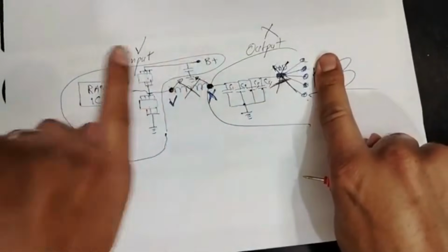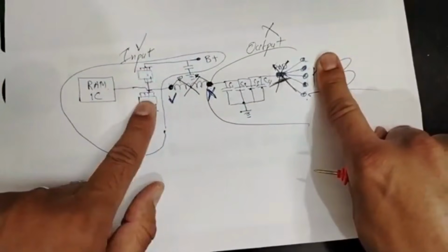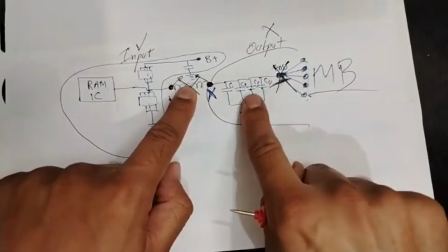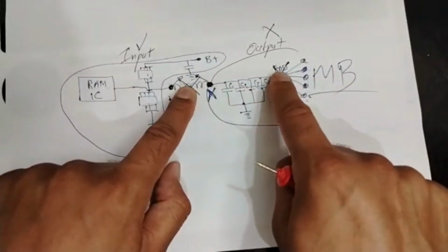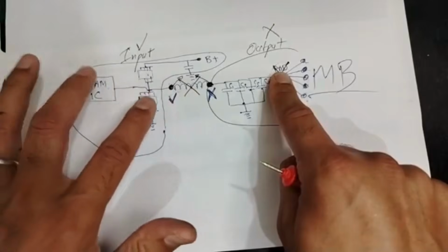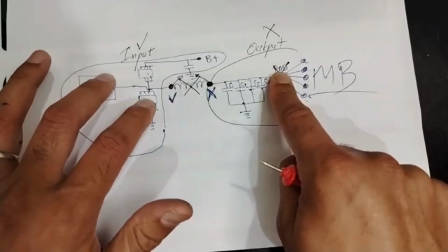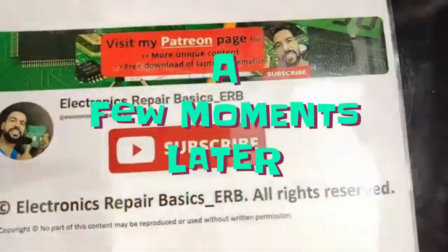I remove just the coil and I find the short in this side. So all those are good. I don't touch any one of these. Just the coil. Now I will not touch anything here. I will just remove the pad. So this process will help you keep this component good. You will not touch anything. Okay, let's find out. Now the pad is removed.